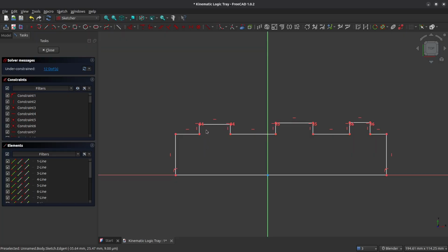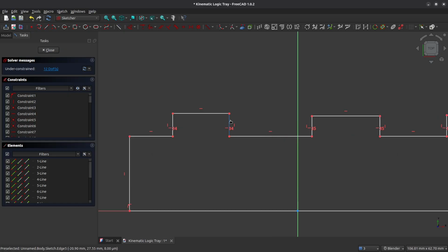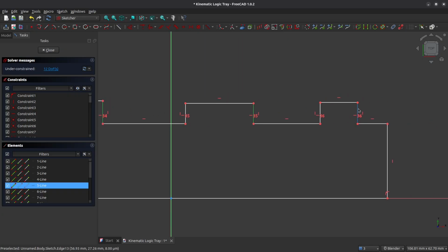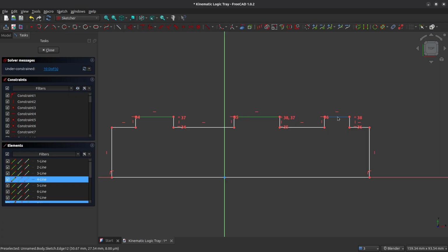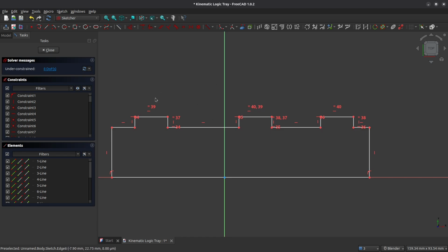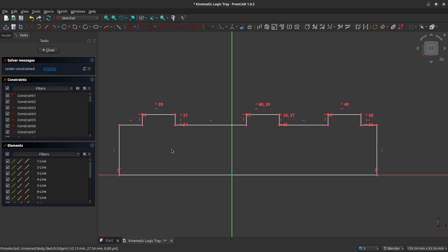And now we're going to make the tab tops so that they are also collinear. We can do that by just grabbing one side from each one of our tabs and setting the height of the tabs equal to each other. So now when we grab the top of one tab, all of them should move. We're going to set the tabs so that they are equal in width. So select all 3 and set them equal.